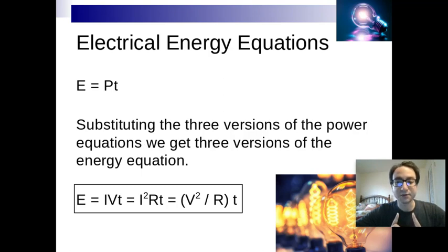And I also will mention here in this video, something I don't have anywhere in text on the presentation. So good question for those of you who stuck around to the end. You know that voltage, current, and resistance all are treated differently, whether we're dealing with a series circuit or a parallel circuit. Well, good news: power always adds up to a total regardless of what kind of circuit we're dealing with.